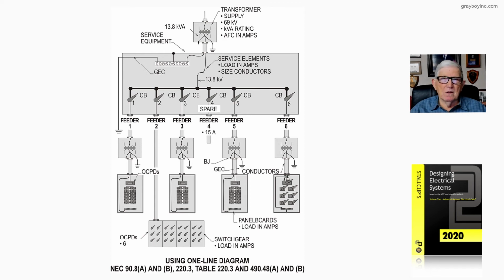Fuses, if you are using fuses to protect systems over 1,000 volts, start with 490.21B in Article 490. Isolating means where you're going to use just isolating switches, to get a complete handle on this now, you need to look at 490.22, 490.21B4 through B7 to really get a handle on it.